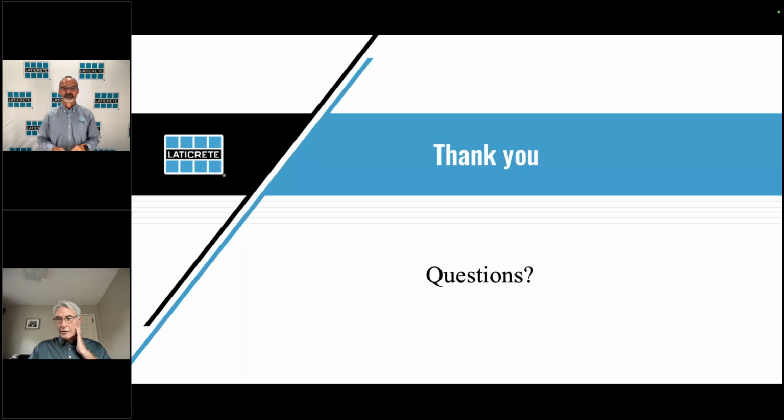All right. What keeps this tile from moving? Just simply the weight of the tile? So it has to be locked in on all the sides. So you're either against adjacent building, concrete, or you've epoxied your live edge down. So it has to be all locked together that way. You can't just throw out a bunch of pedestals. You probably could if it was short, but you still have to lock in the outside ring of it. And that's where you'd epoxy the bottom and then epoxy it all the way to the bottom of the material.